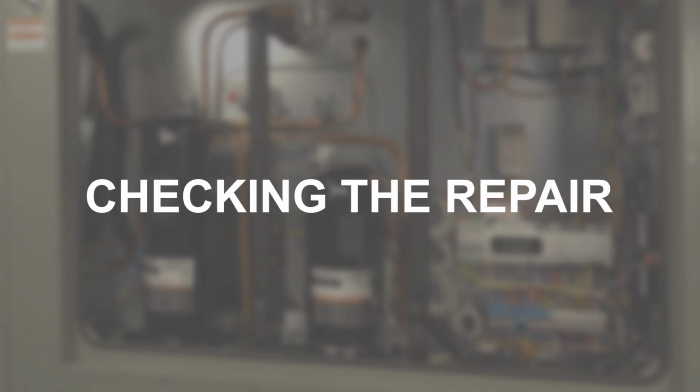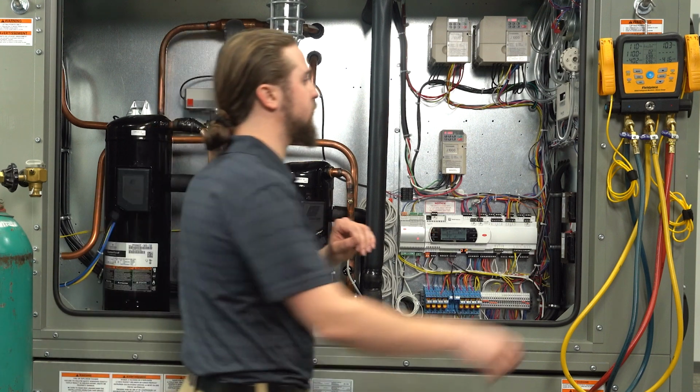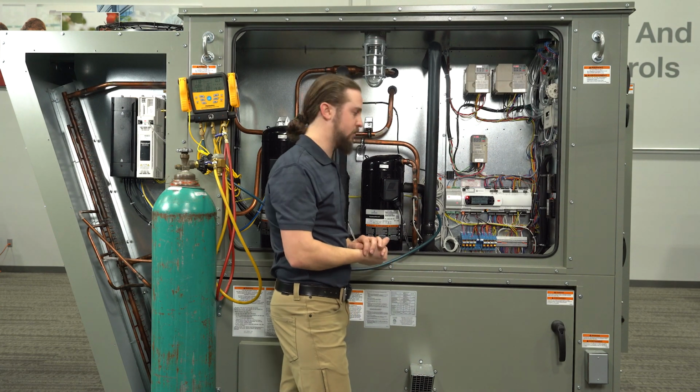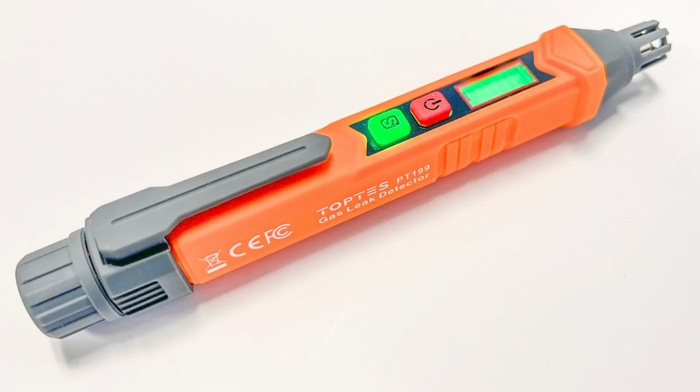Okay, circuit B, we'll fill this with nitrogen. All right, our nitrogen's flowing into circuit B. Check with a handheld leak detection sensor to make sure no refrigerant remains in the system.